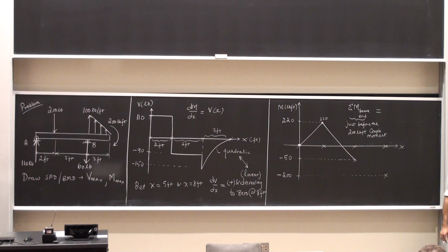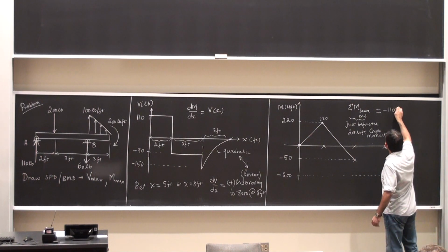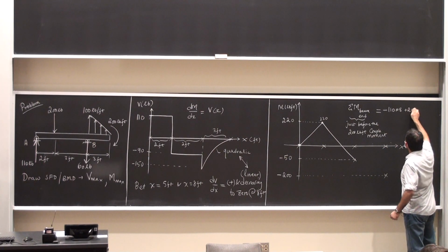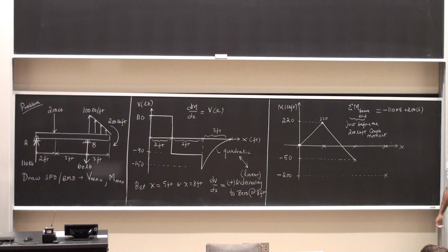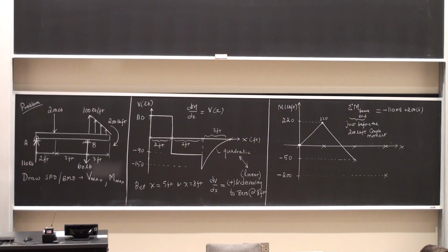I'm doing that just before the 200 pound-feet couple moment, so I'm just looking at the total sum. It should give me what? 200, hopefully negative or positive, we'll see. So that's going to be 110 times 8 clockwise. Then I'm going to have 200 pounds times a distance of 6 counterclockwise. I'm summing moments about the end of the beam, so this is plus 200 times 6. 60 pounds times a distance of 3 feet.